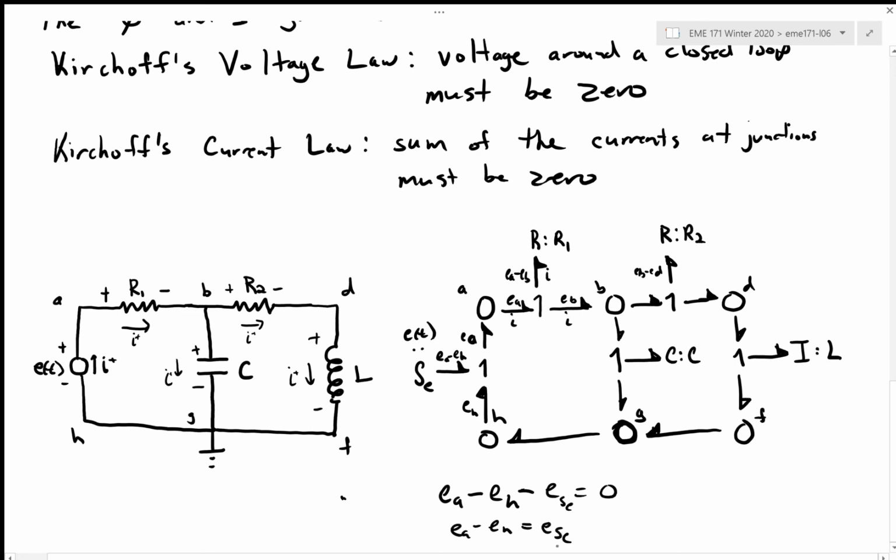Right? So that fits the one junction. I have the proper sign convention. And if EA is a larger number than EH, I have positive power flow into the system. So you want to double check that these summations do have the right signs and you set up the arrows appropriately. All right, so that completes step 3.